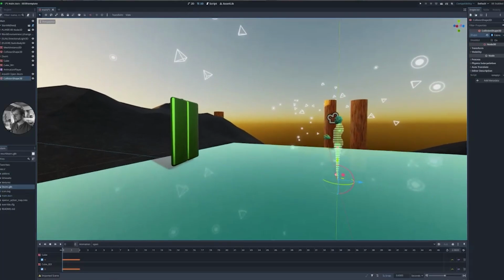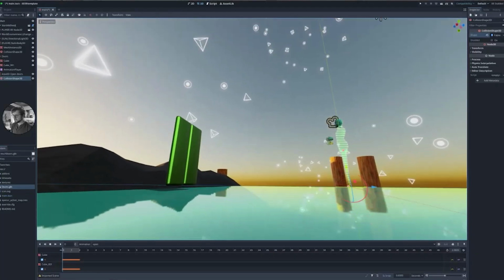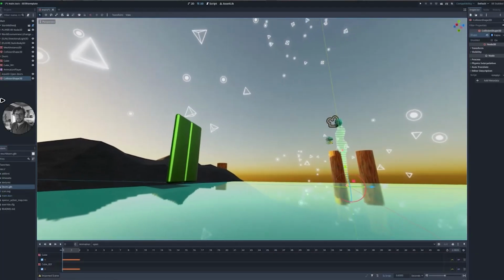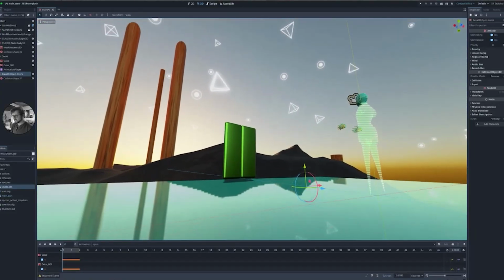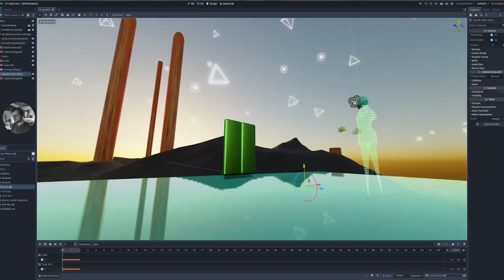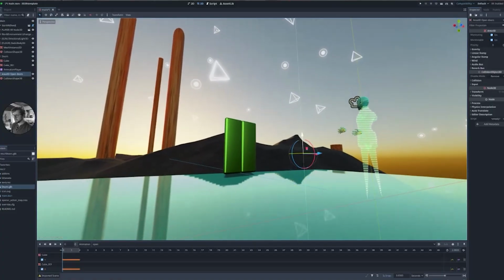All right. So now I'm going to rotate my scene so I have a good view. And I'm not going to click on the collision shape. I'm going to click on the area itself. This is really important. You want to click on the right part of the hierarchy. And now I'll click on the gizmo to move this whole thing forward. And I'm just going to kind of move it at an angle where I can actually see that collision shape because it's a little hard to see. It's got kind of a capsule outline on it.